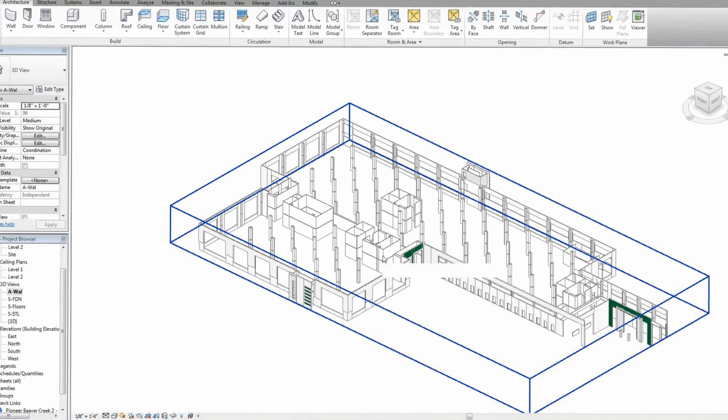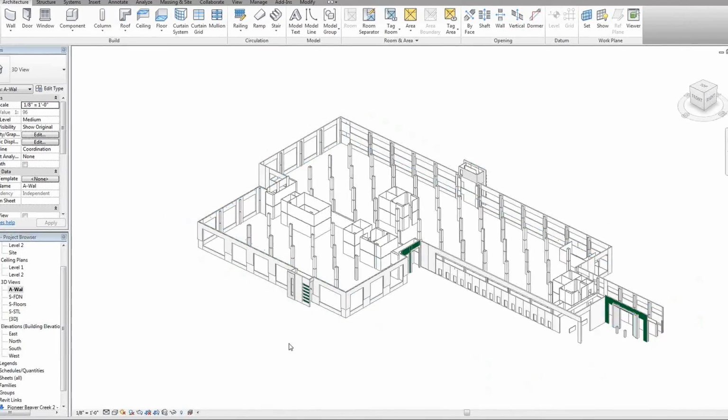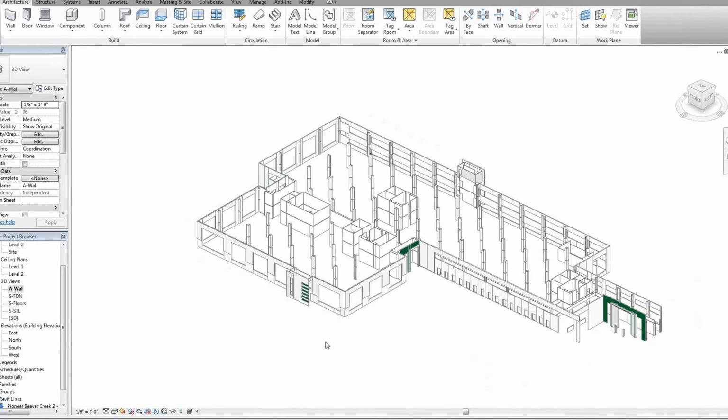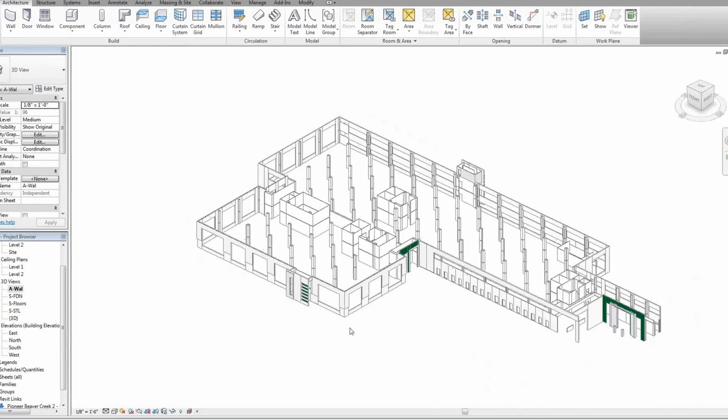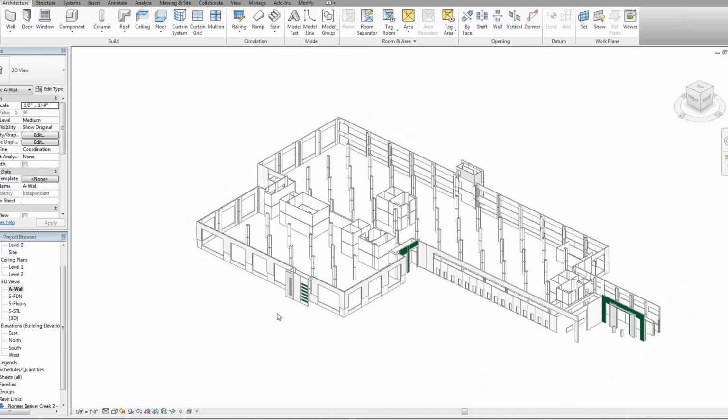What you see, though, is you have a bunch of interior walls, and typically I recommend that you separate interior and exterior walls. It'll help you out in Navisworks when you do clash detection, and also in Synchro, too, because usually you've got good detail for scheduling the exterior walls and these tilt panels, but maybe they haven't really detailed out the interior walls, so maybe you don't want to see them.